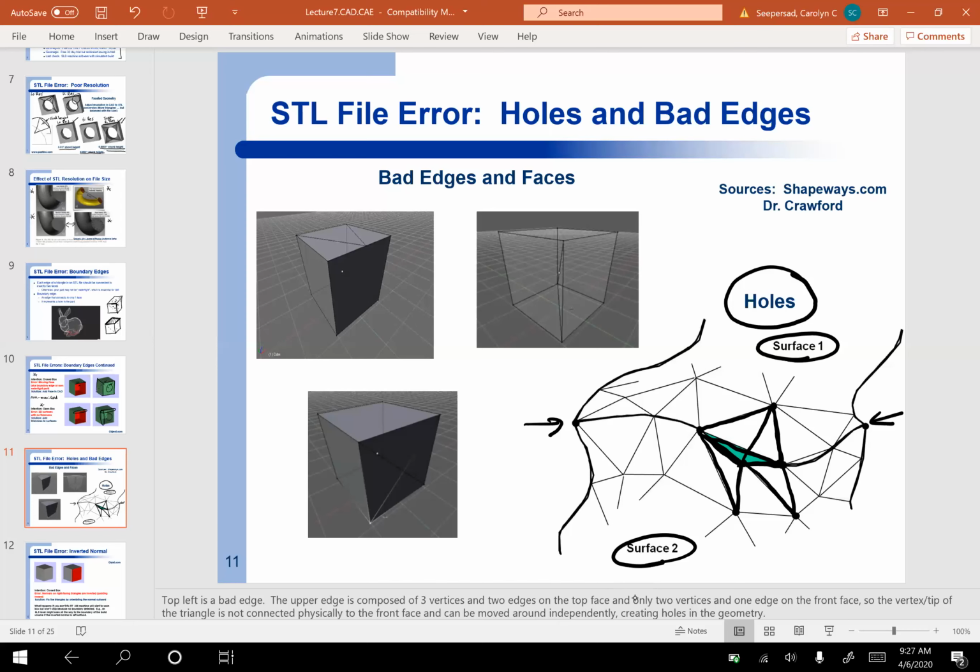So if you have a hole, the machine can find it very difficult to build that. As it's process planning, what it typically does is it'll move across the build envelope until it gets to a triangle and intersects with it, and then it'll start building. Then as it goes through the part and exits the other side, it'll say, oh okay, I've intersected with another boundary triangle, I need to stop, provided that the facet normals are oriented in the right direction, towards the exterior. But if it encounters a hole, it doesn't know to stop.